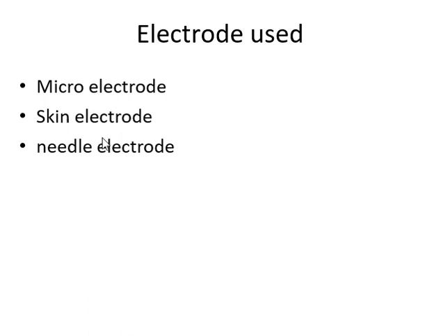And the next one is skin electrode. Skin electrodes can register eye movements recorded by the change in the voltage difference between the anterior and posterior eye pole. What are skin electrodes made of? Electrodes can be made from any conductive material depending on the nature of the application. Electrodes may be made from graphite, noble metals like gold, silver, or platinum. Copper, titanium, and brass are also commonly used.